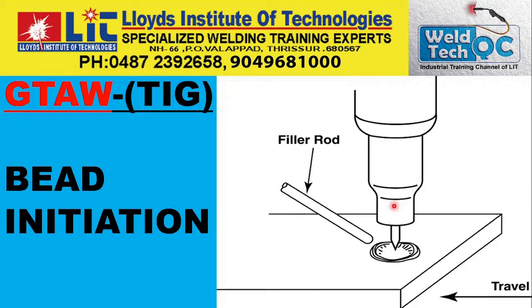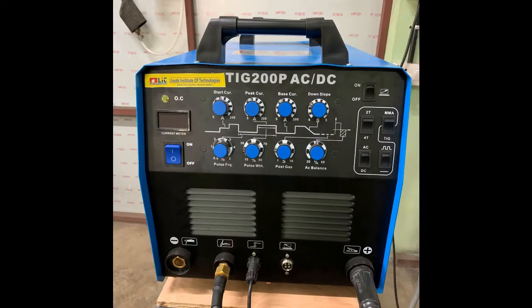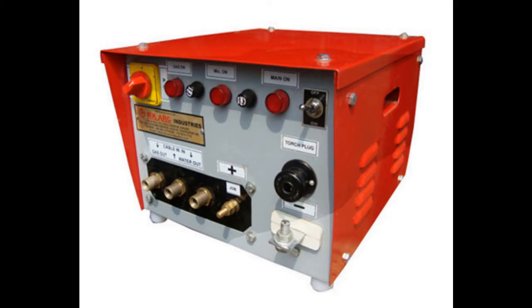And let us see how the bead initiation is done. The torch is moved in a small circle to establish a weld pool. Touch start is not recommended because it could damage your tungsten electrode. So use a high frequency arc instead, so that you don't have to touch the electrode. The arc is established just before touching if you are using a high frequency arc.